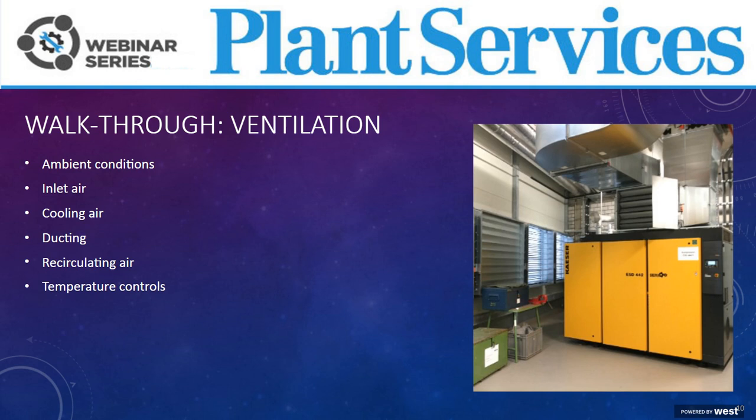Like we discussed, ambient condition of your room, both on the low and the high end, can affect operation of this equipment. If the room's too cold, compressor oil may be too viscous, and possibly if there's any standing water in your equipment, that could freeze. Therefore, all compressor manufacturers give a minimum operating temperature threshold. This is usually above the freezing point of water. Likewise, coolers, motors, etc., those are going to be sized for specific temperature ranges. Operating above a certain temperature can shorten the lifetime of your equipment as well, basically reducing your reliability.